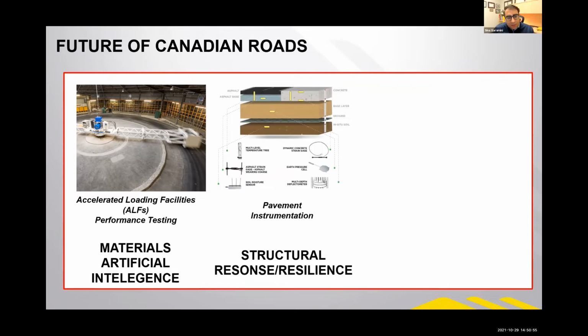Then what we do is we look at the pavement instrumentation. These are instruments that get placed throughout the layers of pavement, and really enable us to understand the stress and the resultant strain, or how much pressure is being disseminated down to the subgrade level, and really allow us to gauge ourselves against the baseline of the pavement adequacy when it was established at the time of construction, and then help us gauge the deterioration rate for the pavement when it comes to future in-place performance.